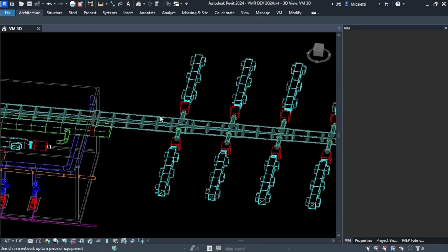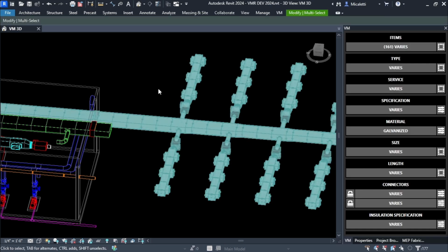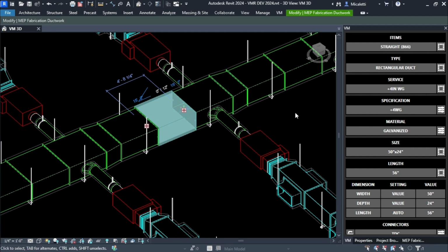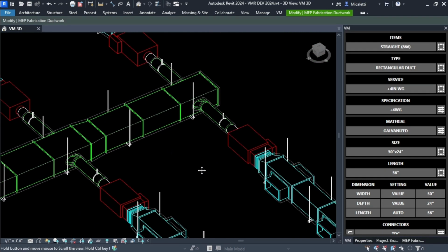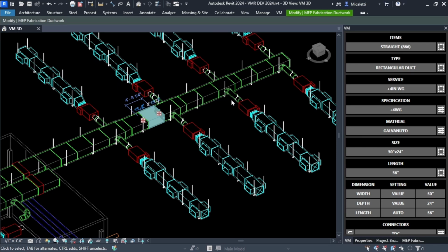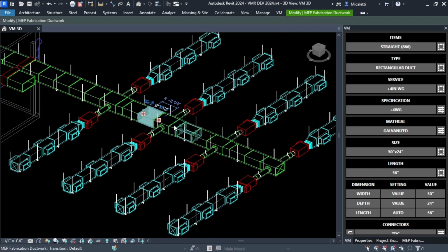Then what we can do is go ahead and select all of this and use the hotkey for auto hanger, VAH. Now, our hanger algorithm does coordinate with taps and Olets. No other hanger algorithm does this, which basically means if you're working with taps and Olets, then their hanger algorithms are useless. You're much better off just putting them yourself because they're all going to be wrong. So that's one thing that it does do.